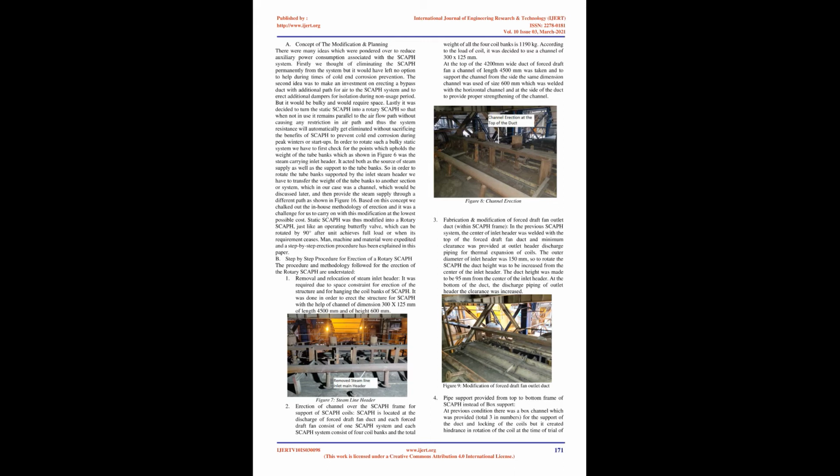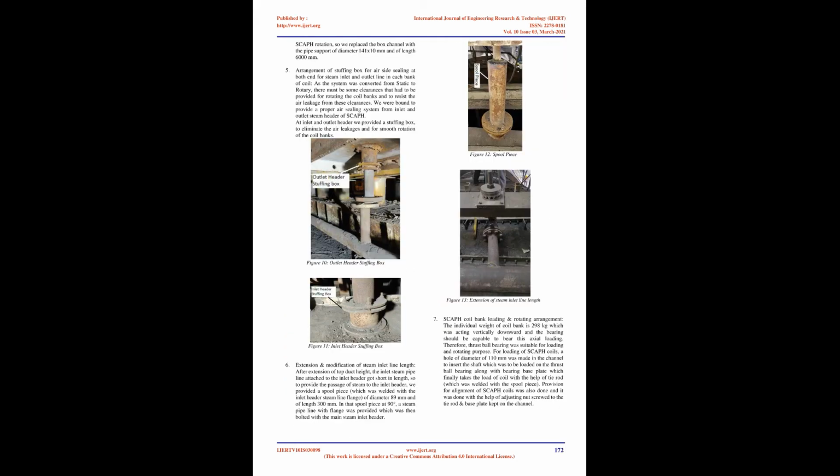SCAF is taken into service when ambient temperature falls and reduces the flue gas outlet temperature of APH. SCAF is also taken into service during unit startup and low load operation. Generally, in unit startup till synchronization oil guns are kept in service, but due to various changes in material composition of boiler and change in operational philosophy, nowadays mill is taken in service prior to unit synchronization. But there are some prerequisites that are to be followed prior to taking pulverizer in service.